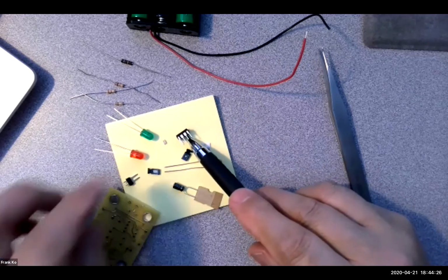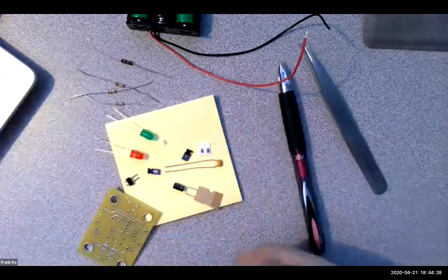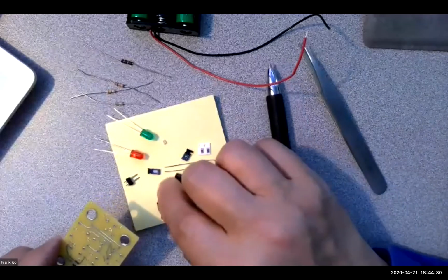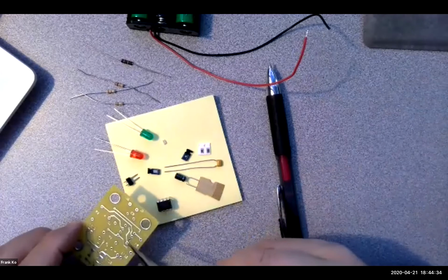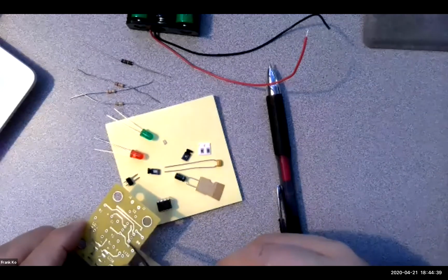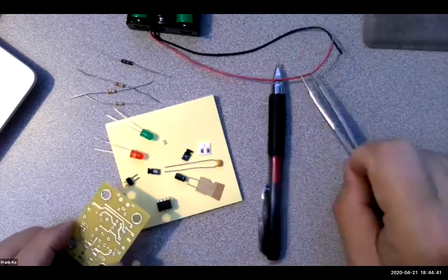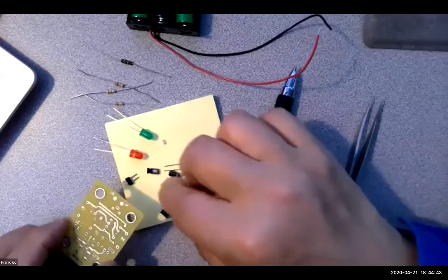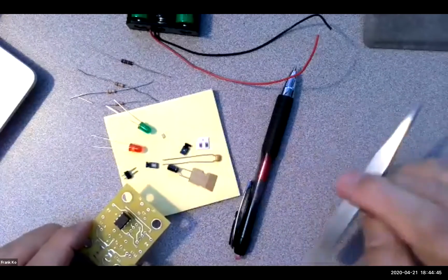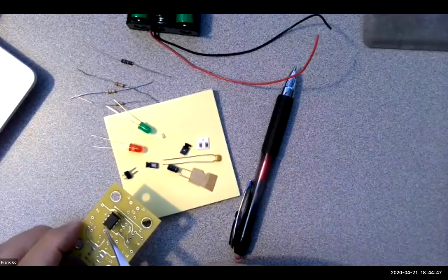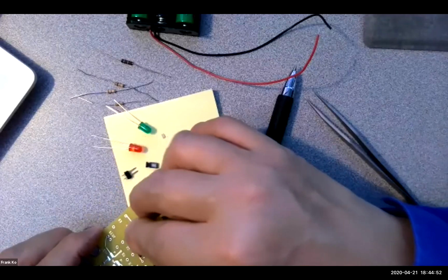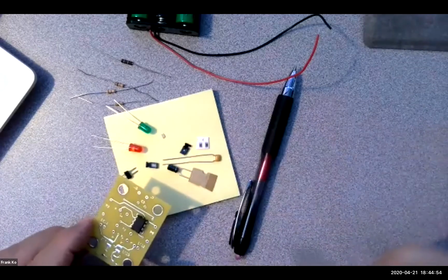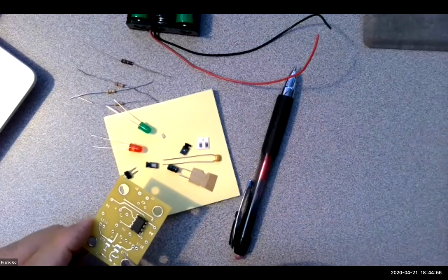And when you're soldering the chip in place, very important, make sure the orientation of the chip is correct. The orientation of the chip is set up such that it goes on the board right here, and there's one square pad. That one square pad on the board is where the notch side of the chip goes. Notice that the chip happens to have a notch on one side, so the notch identifies pin 1, and it goes in that way. So that notch faces your LEDs.